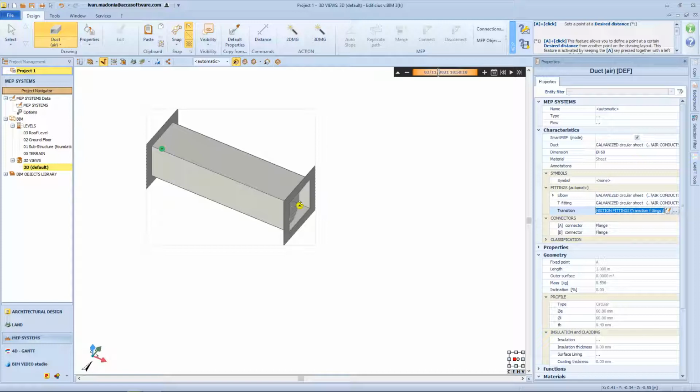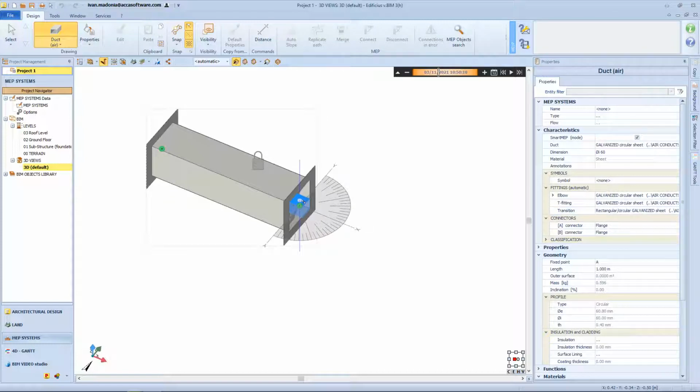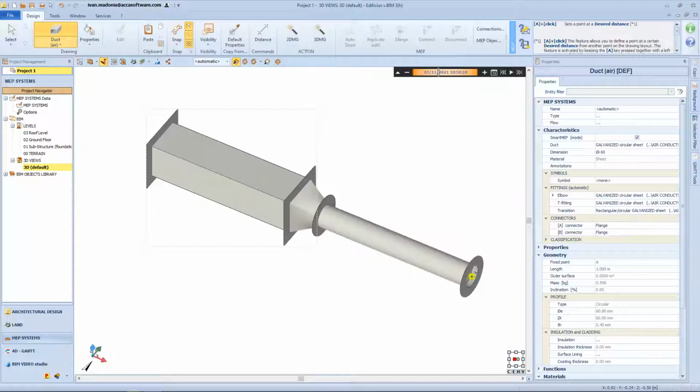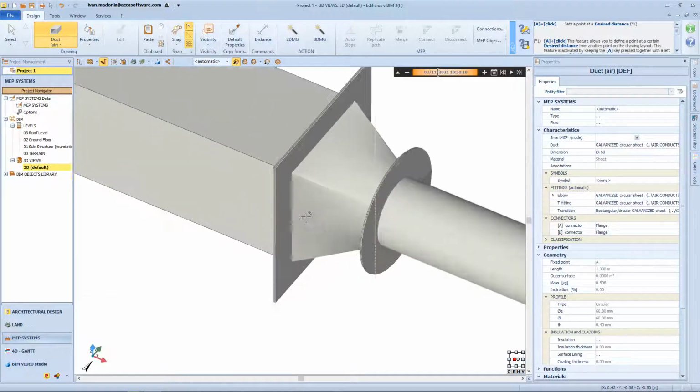The first point of the pipeline is then positioned on the connection using the yellow connection snap. In this case, the menu that allows you to apply the most suitable size or the one selected from the catalog to the pipe does not appear, as the shapes of the profiles are different and the size will be the one set in the Properties toolbox. By following the 0 degrees angle snap on the protractor that appears by default, it is possible to trace the pipe on the axis and obtain the rectangular-circular transition with the Smart M.E.P mode.